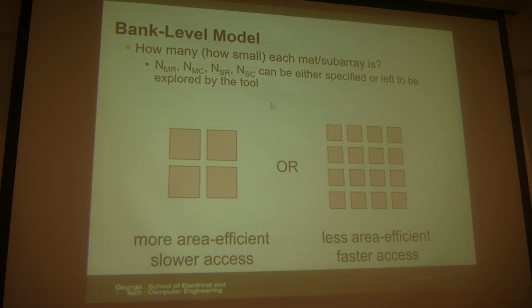So the question for the high-level design is, how do you size each mat or sub-array? Let's say you have a total capacity of the memory. How do you design the size of each mat or sub-array, or how many sub-arrays become one mat? So those are the design questions from the system's perspective. For example, those are two possible designs here.